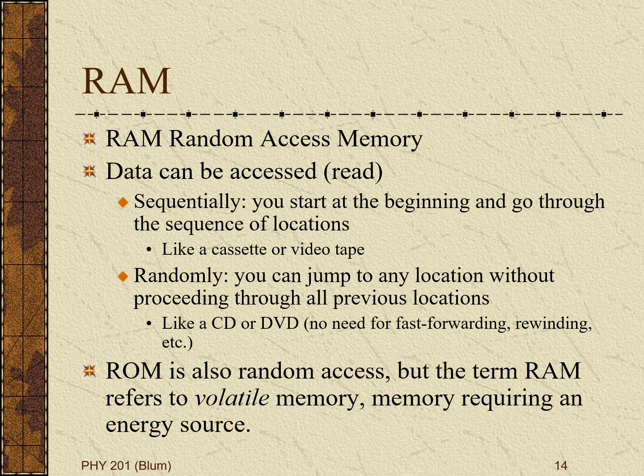In your mind, your code has some logic to it, so you don't think of it as random, but as far as the device is concerned, it's random. You provide the address, you go to that address, it doesn't matter. And so actually, ROM is RAM in that ROM uses a decoder and is accessed randomly. ROM is not sequential, ROM is random access.